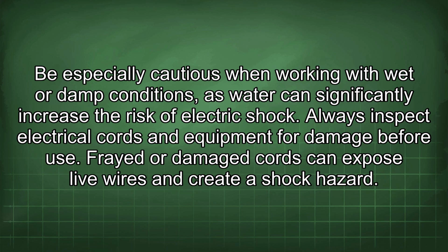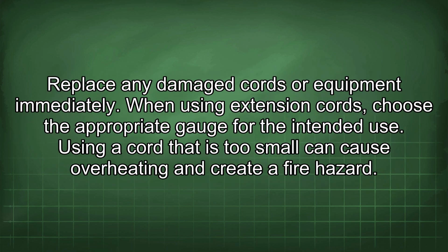Always inspect electrical cords and equipment for damage before use. Frayed or damaged cords can expose live wires and create a shock hazard. Replace any damaged cords or equipment immediately. When using extension cords, choose the appropriate gauge for the intended use. Using a cord that is too small can cause overheating and create a fire hazard.